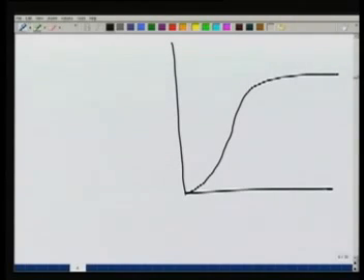Now once we get the S curve, suppose we now shift this S curve by some amount, let's call it delta t. So this is an S curve obtained from a d-hour UH. So let's call it a d-hour S curve. And then we shift it by an amount delta t.